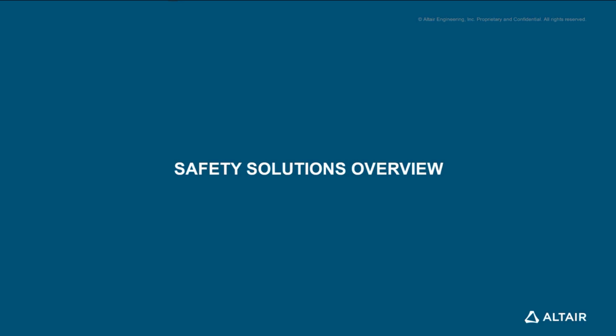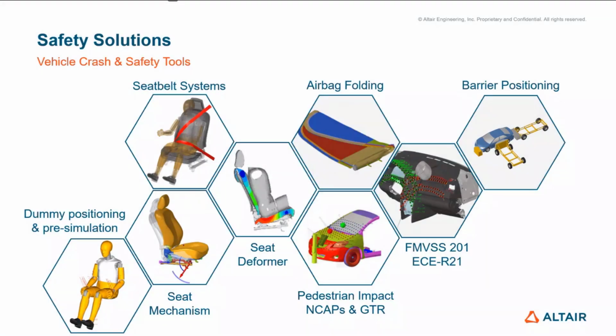Let's move now to the safety solutions overview, just to recall everyone what we support today in the crash and safety applications and occupant safety applications. So we have, I would say, all the tools for the occupant safety application which are requested today, like the dummy positioning, the seat mechanism, the pre-simulation tools to deform the seat and the dummy, the creation of the seat belts, and in terms of impact analysis, we have pedestrian impact tool for pre and post, IP impact tool covered for pre and post, and the barrier positioning automation tool, which positions the barrier depending on the selected load case.